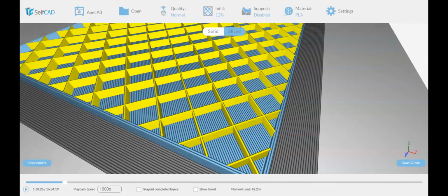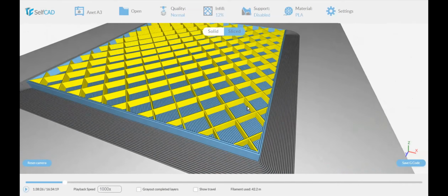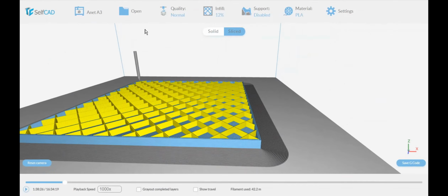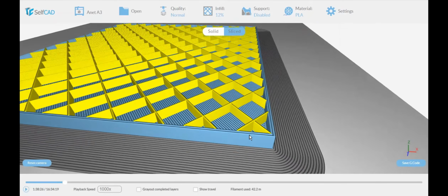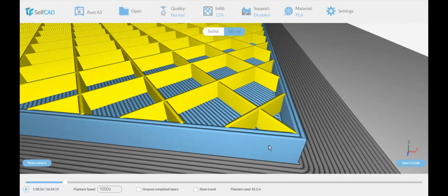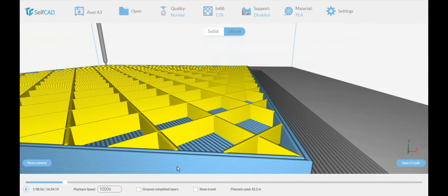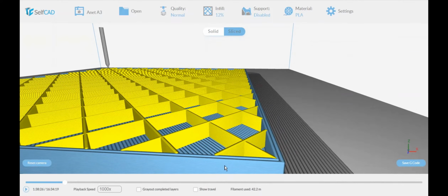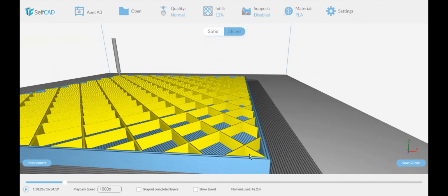Now the quality of this is basically determined by the thickness of the layer, and the thickness of the material, and the material settings have to do with other things, which is based on heat, how much it should heat up the material, and how fast it should move. There are a lot of other settings that we'll see later that affect things, but that's basically the concept. What you see over here is the layers shown as individual layers, and you can even see around 10 layers going on over here. They're all visualizations, but that's the concept.